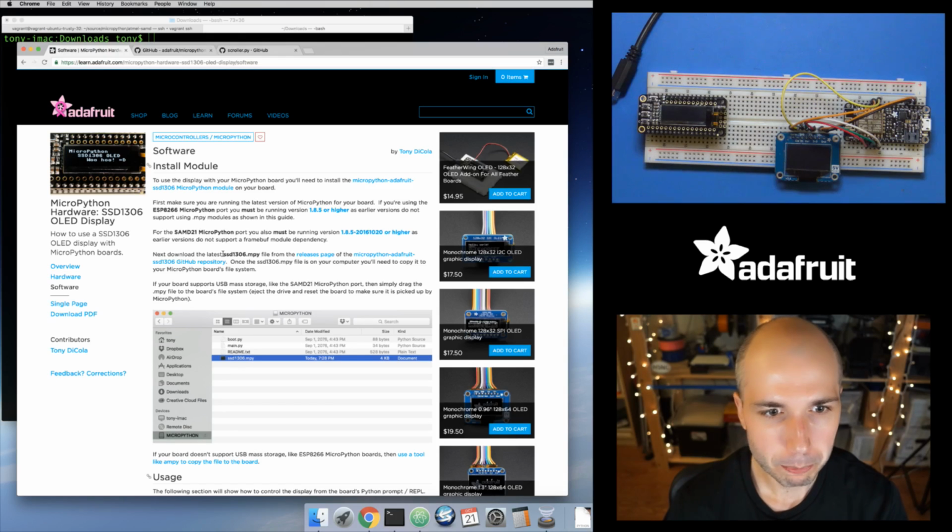There's actually some new support, and so I do mention here you need to be running the very latest version of MicroPython for your board. So for the ESP8266, you need to run version 1.8.5 or higher, and this only came out like a week ago as of the recording of this video. So if you've got an old board lying around with MicroPython, go and update it, because you do need this latest version. In that version, they added support for importing these .mpy module files, and so you really have to have that support for this.